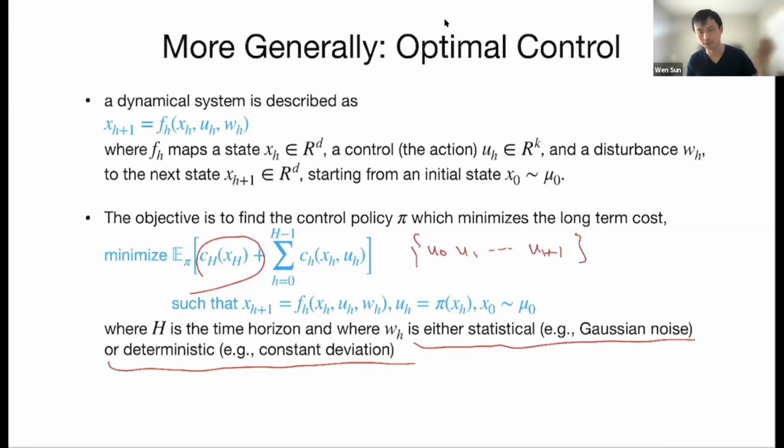If you ask it to move to X', Y', Z', it also moves to X', Y', Z' plus delta. In other words, if you command the robot to go to some particular position, instead of going to that specific position, it often goes to that position plus some deviation delta. And that delta is usually a constant. That happens a lot, and usually you have to recalibrate the robot after using it for, for instance, several days.